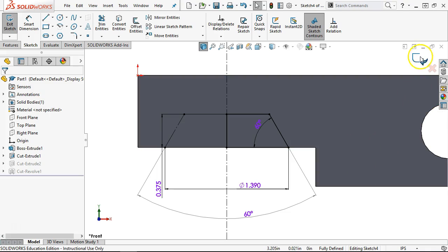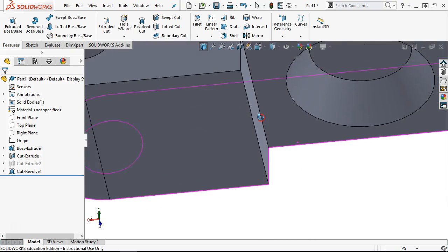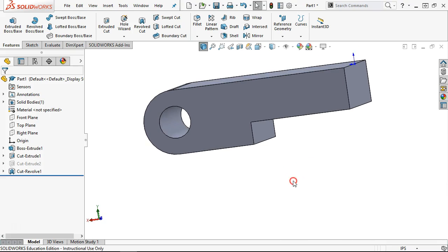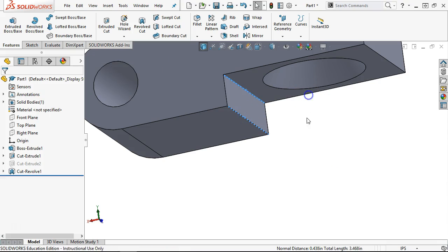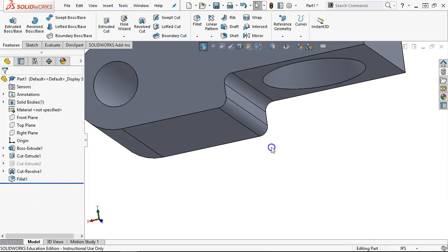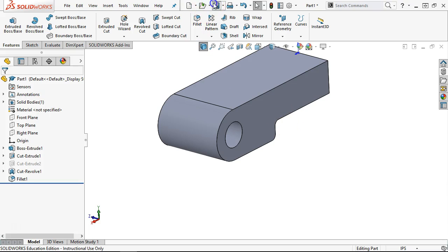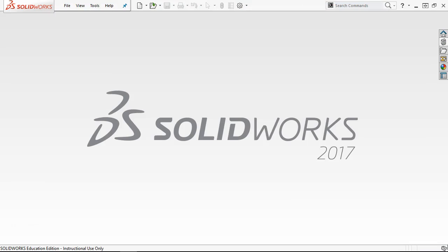All right. So if the geometry doesn't make sense visually, then we'll go back and we'll make some adjustments. All right, the 2 radiuses on the inside then, the fillets, we'll put those in last, 0.125. And accept. Alright, I think that was it. So we can save that one. That was item 5, the clamp. And we'll go ahead and close that one back.